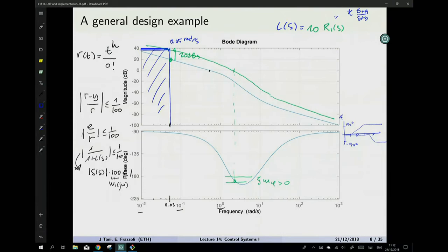Okay, so where were we? We were at the point where we agreed that we had to design a lead compensator to increase the margin of phase. How do we go about choosing the A and B, the pole and the zero, in order to do this?